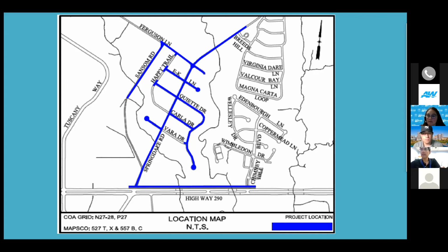This project has been long coming, and getting it to construction. I think I'm sort of answering the next question as well. We're going to address the high pressure. But I believe all houses in this area should have individual PRVs. If you don't, then your plumbing's subject to 150 PSI or so. So I would think everybody has individual PRVs.